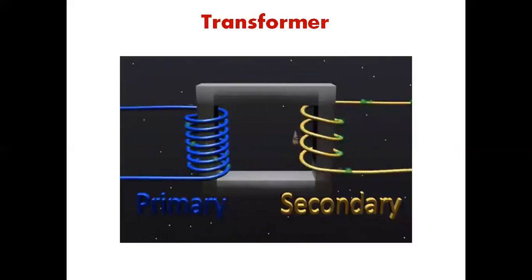The basic fact that generation is inherently a production of alternating EMF, together with the advantage of AC transmission using highly efficient stationary transformers, became the main reason for the widespread development of AC systems. Besides this, transformers are also used in rectifiers, starters, furnaces, welding, traction systems, casting units, etc. As compared to a rotating machine, a static transformer is much simpler because of the less complex interrelation between the magnetic and electric circuits.